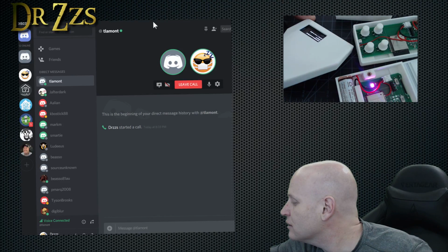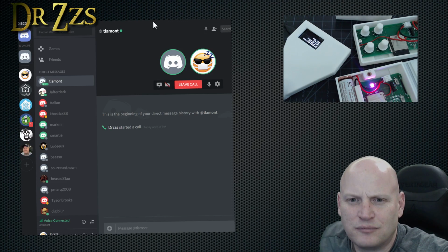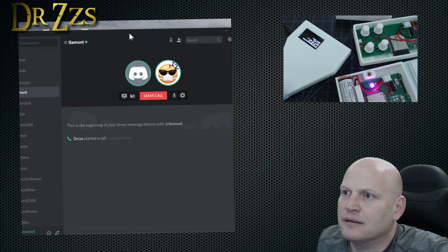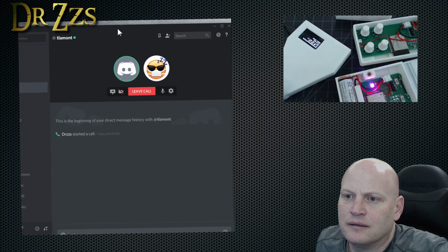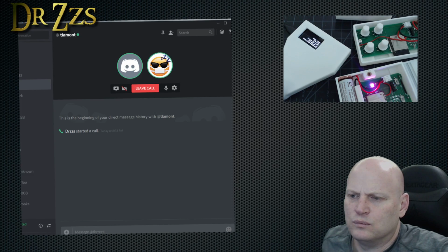Rob's question about the LED. If I can just answer Rob's question about the LED. Oh, sure. I use the WS2812B LEDs mainly because I have reels and reels of them from other projects. I ran into an issue with them where even when the light's turned off, they draw nearly 380 microamps of power. Ooh.